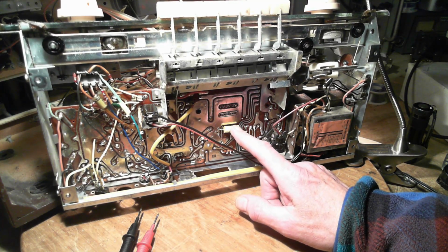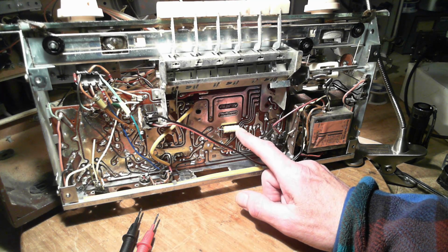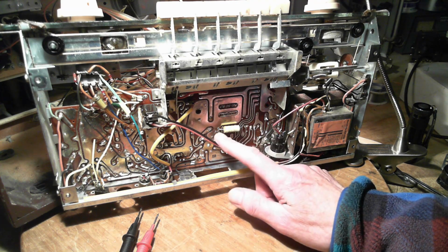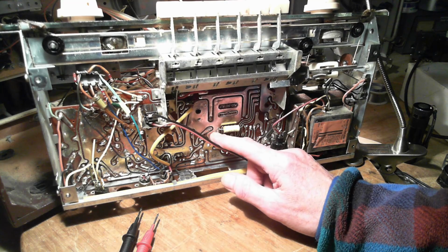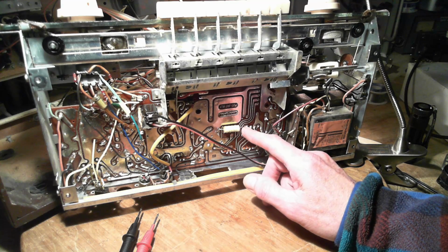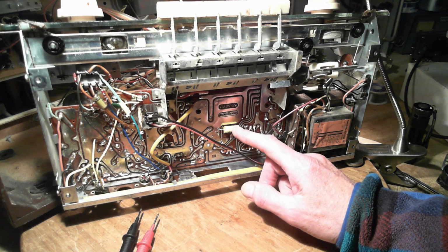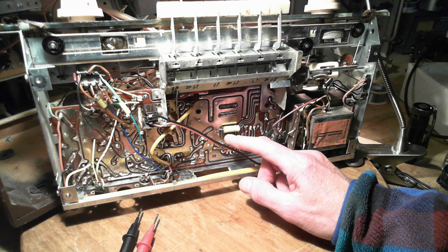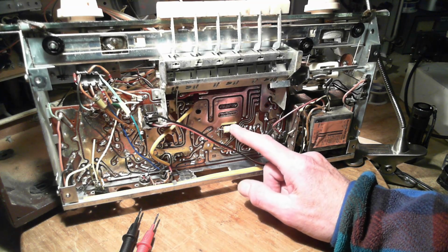What would it matter? But it is possible that I put this capacitor in so the outside foil is connected to the high impedance side of the circuit that the capacitor is in. One side is this ground area, and the other side is going right into the IF cans. So we can guess this is a high impedance connection. So if the outside foil is connected to this lead, then it's pretty easy to imagine that there's some interaction going on between the capacitor foil and this weird zigzag thing that's in behind here.